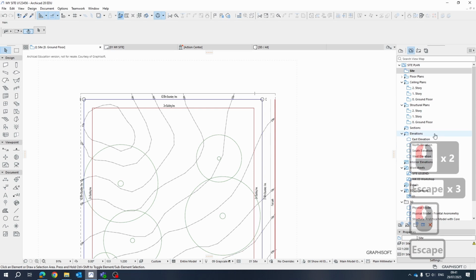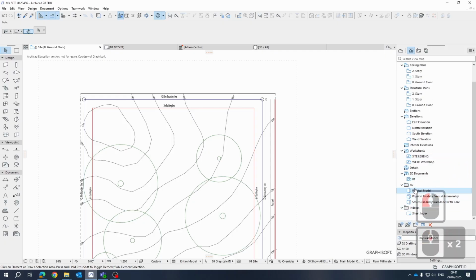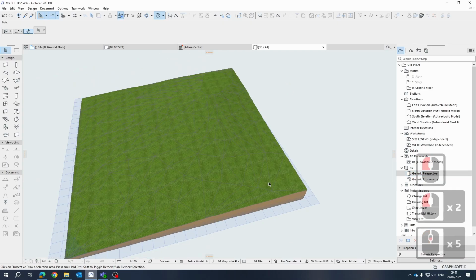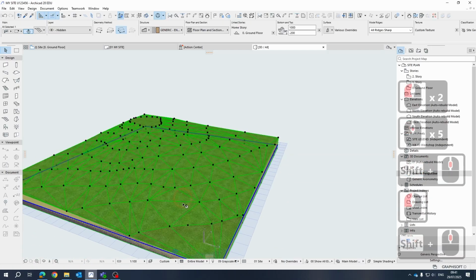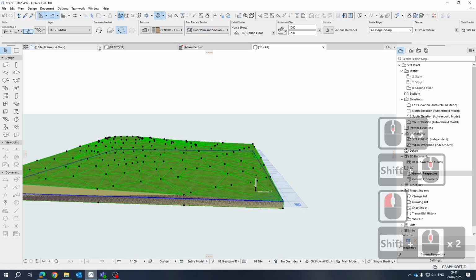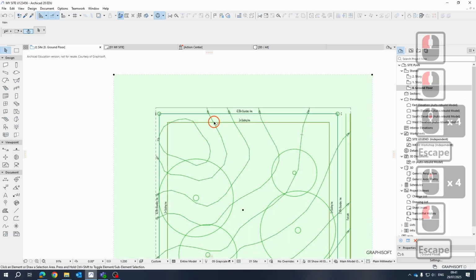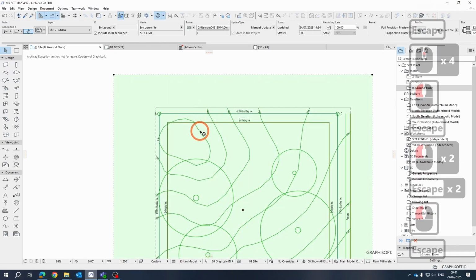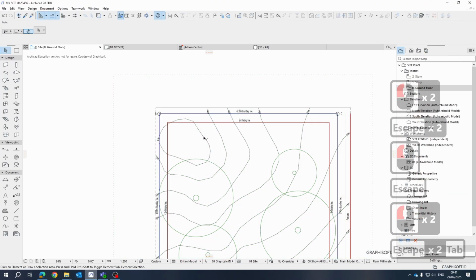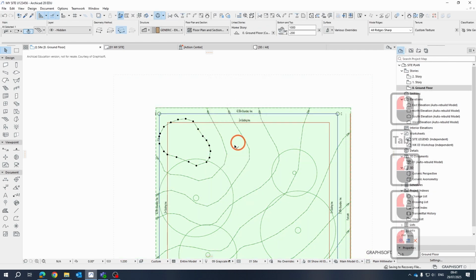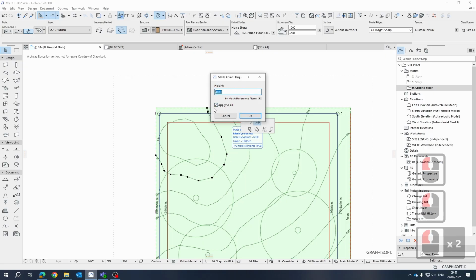So let me just go to 3D view. So I just want to go to 3D, so 3D view, just the basic 3D view. Okay, so you can see that it has started to identify the heights for us. Okay, so that's actually quite straightforward. So once we've got our topography and it's extracted, it's got the information from, so just tab, select the mesh, tab again, select the mesh, pick these, so that must be 4,500, pick those should be 4,000.